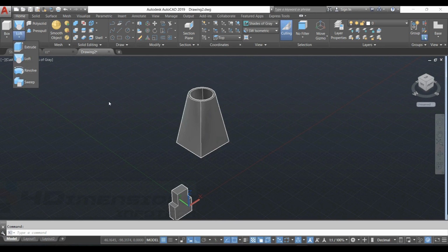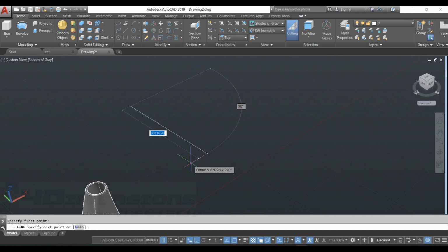For that we are going to make one axis and one profile which is going to revolve around the axis. I'm going to make one shaft with overall length of 400 mm. Now we'll take the cross section sizes 50, then inner length I'm going to take here 60, next 70 as a radius. This length I'm going to take 150, and then here I'm going to take the length as 80, and we are going to match it by the end in this way.